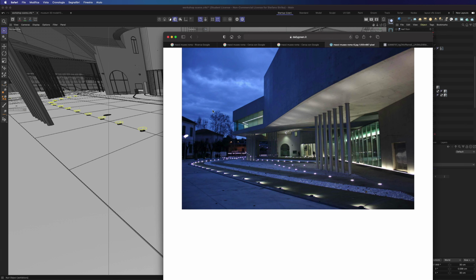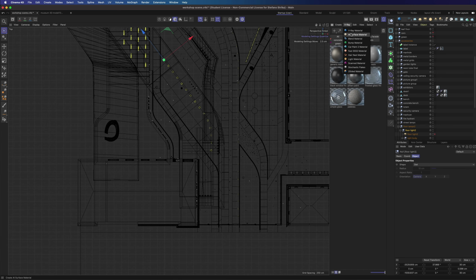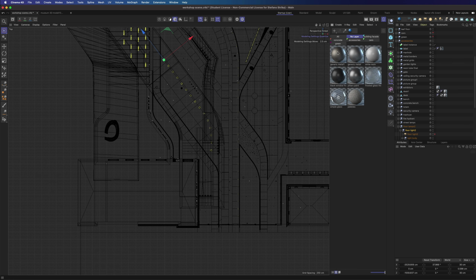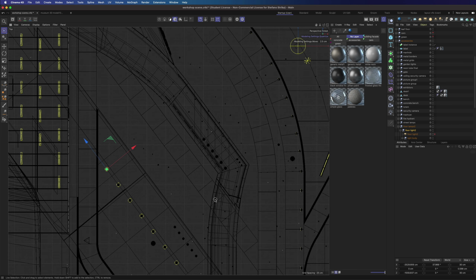And now we can see how to add this kind of linear light up here. Linear lights can be inserted in various ways, through light material or simply through a self-illumination channel of the V-Ray material. But these options are not optimized for the sampler, therefore I tend to avoid them whenever possible. Since in this case I have an almost linear situation, I prefer to distribute some simple area lights instead.